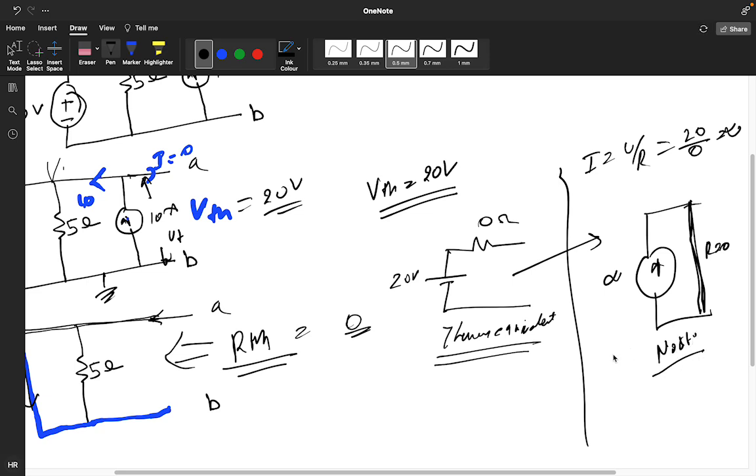So we cannot say the Norton equivalent is applicable. We cannot make a Norton equivalent circuit for this circuit. Whenever you are getting the RTH value as 0, for that you cannot make your Norton equivalent circuit, because you are getting a circuit like this, so this is an irrelevant circuit. For the above given network, we cannot develop the Norton equivalent because it is not satisfying KVL.